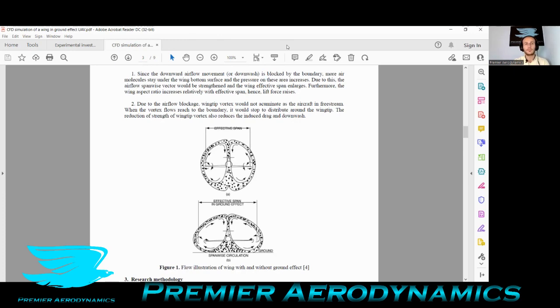So that's how the ground effect works. Coming back to this paper, which now goes into some experiments which tested this particular type of aircraft in different conditions, different heights from the ground, and with a different configuration, the end plates. End plates help to increase the performance of the wing through moving its center of pressure forward to the leading edge. The influence of the end plates on the aerodynamic characteristics of small aspect ratio wings was studied by